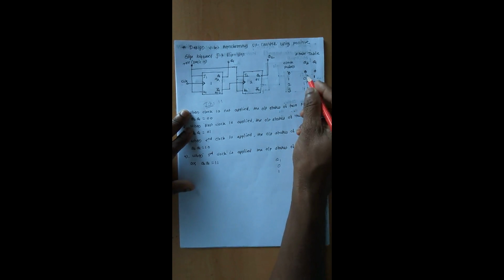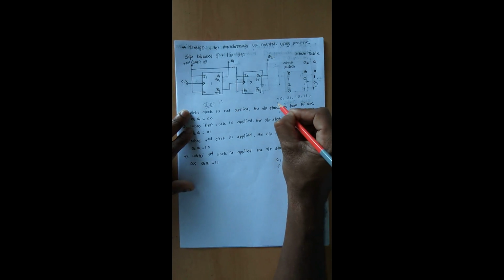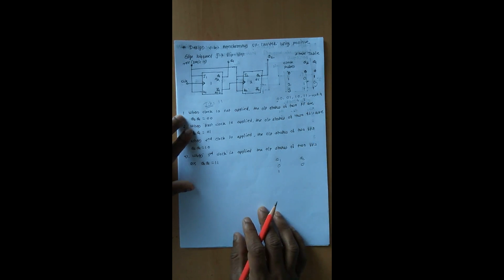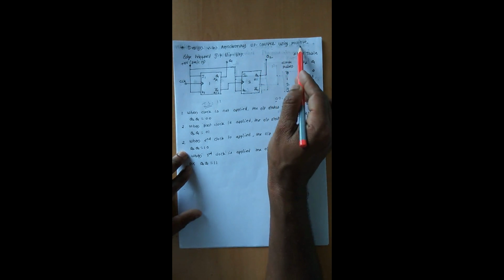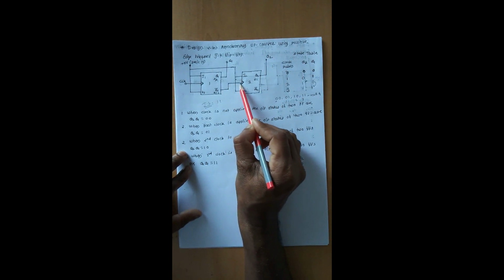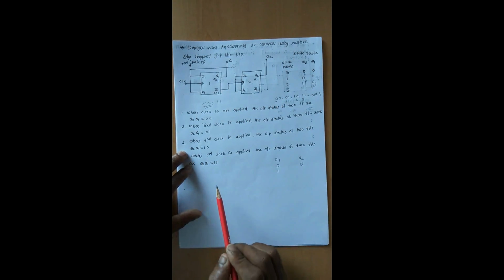Okay, so if you observe carefully, this is a 2-bit up counter which counts 0 0, 0 1, 1 0 and 1 1. Hence it passes through 4 different conditions: 0, 1, 2 and 3. Hence it is called a modulus 4 counter. One more condition is that we implement the up counter using positive edge triggered flip-flops, so we have to use the complement output as the clock to the second flip-flop.